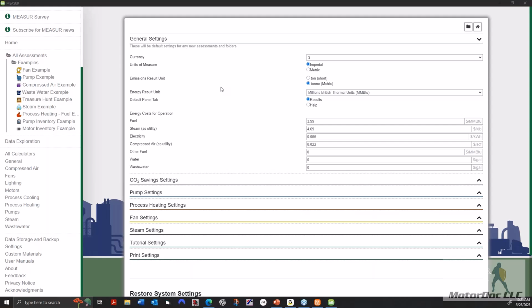We found that if I meet a standard alignment, basically what's considered good based upon publications and not a precision alignment. Precision alignment, you only increase the losses as far as friction and windage, and that it's also hard to define precision alignment because I don't think there's an actual value for that, even with the new standard.